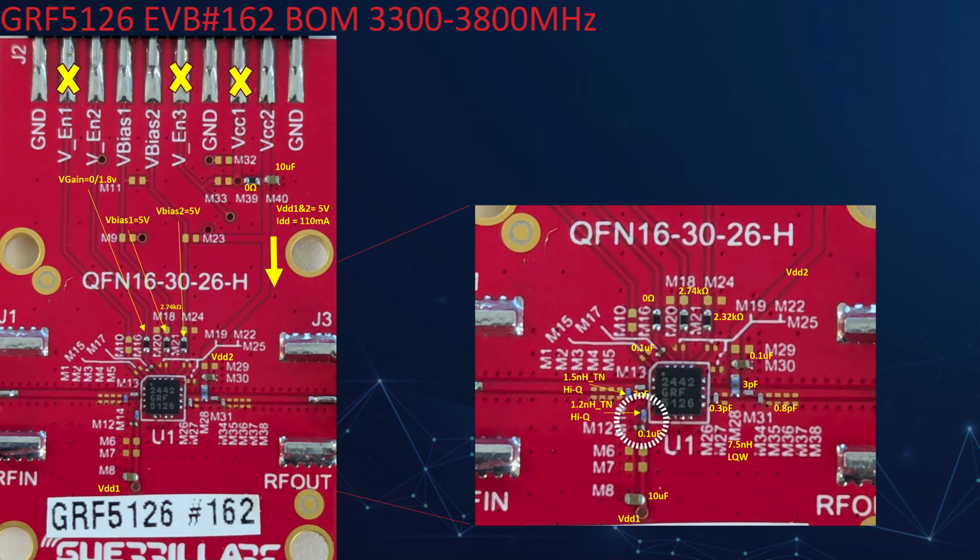And I'll look at a couple of different locations of that and have a separate set of S parameters. So further away from the part, I could tune the maybe 4 to 5 gigahertz range, and then as I push it closer to the part, I can go higher in frequency.